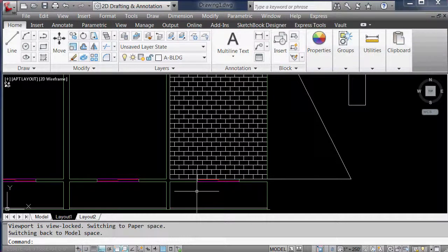Okay, now if you're set to architectural units and you're set 1 to 1, you can be guaranteed with this particular hatch pattern that it's going to come in at its proper scale. Okay, which is, if you're dealing with 8-inch cinder block, it's going to be 8 inches high and 16 inches long. AutoCAD did that purposely so that architects can put in their blocks and they're going to be scaled correctly. Now you have to remember that AutoCAD was made primarily for architects initially, and then it just kind of branched off.